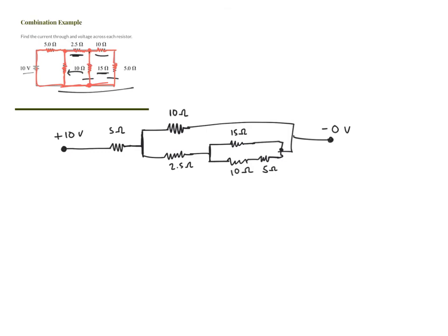So that is the whole circuit drawn out in line form, which is a little bit easier to understand and evaluate. From here, I'm going to start simplifying this until I get basically one giant resistor instead of all of these little ones. The first circuit part I'm going to simplify is this one down here, the smallest parallel circuit, which has these 3 resistors. To evaluate this, you can add up the 10 ohm resistor and the 5 ohm resistor.